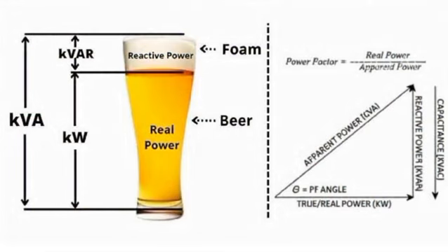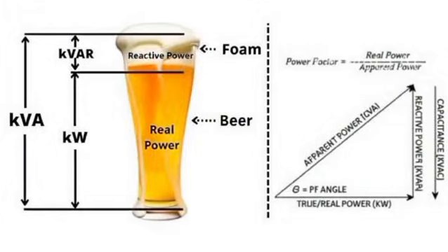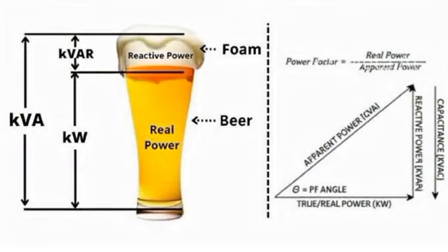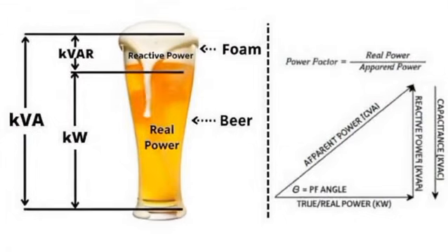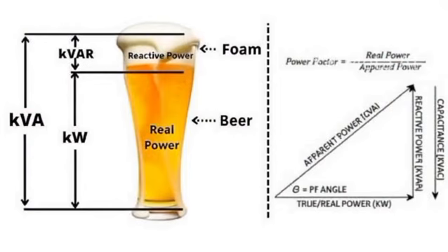In DC circuits, one can evaluate the power of the circuit by finding the product of readings of voltmeter and ammeter. While in the case of AC circuit, the multiplication of these two provides the apparent power but not the actual power. This is so because in AC circuits, the total supplied power, for example the apparent power, is not solely utilized by the circuit. The actually utilized power by the circuit is referred to as true power.